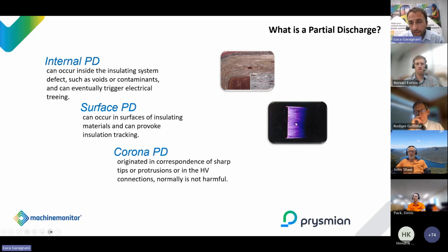If the layer is not installed properly, like you can see here, probably at this line, and there is a gap between the slot coating and the stress grading, you basically have 50% of the voltage of the bar in a few millimeters of surface. That obviously causes a discharge on the surface of the bar. This is a very common surface discharge. And we will see in the presentation that the same problem can be found in cable terminations and bushings. So it's a very common issue.